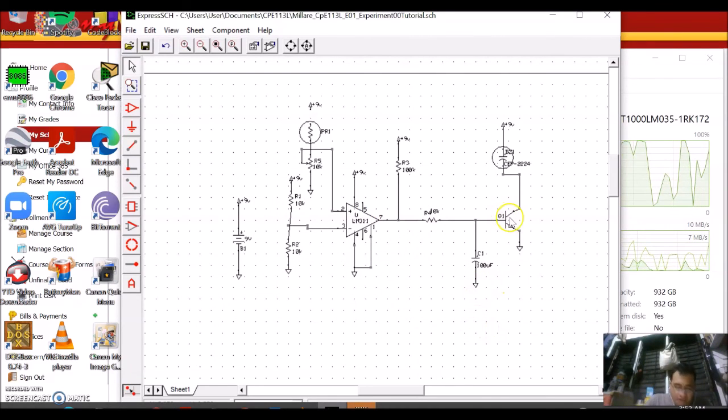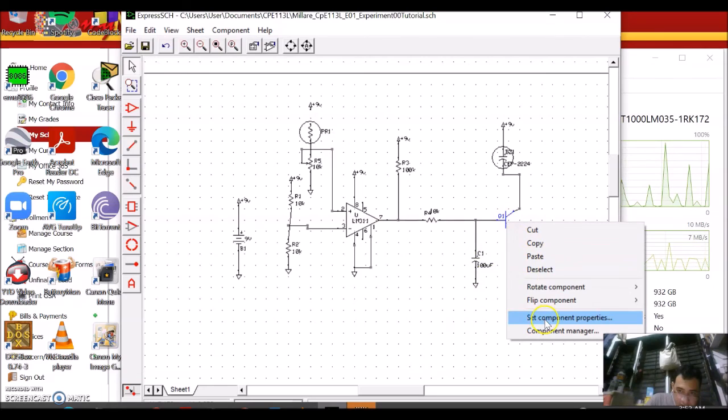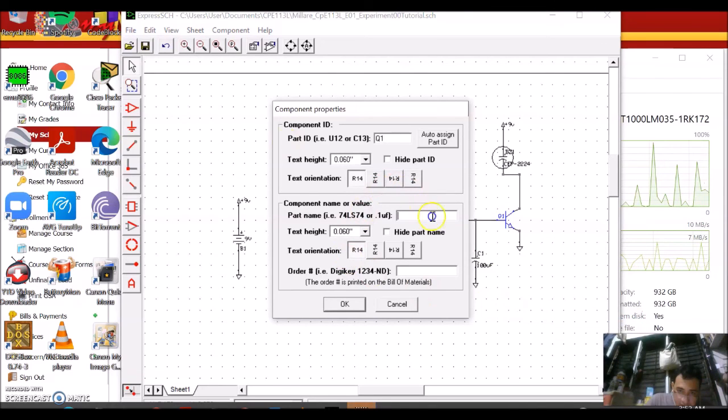And then we'll have to put a value. Since the pins inside of the BJT right here in this area are not specified, this is because pin assignments vary for different BJTs. So one would possibly be able to see an error message. So we would just have to place what we call here a value at this point. We would call this 2N1711.